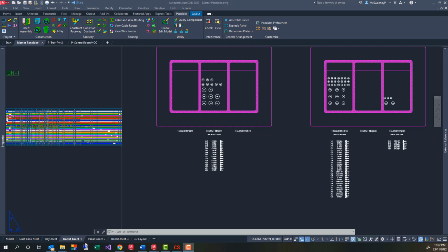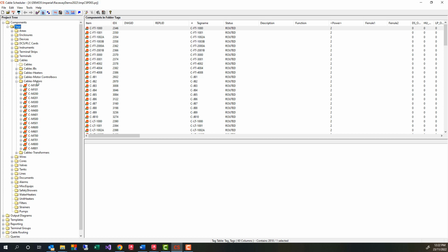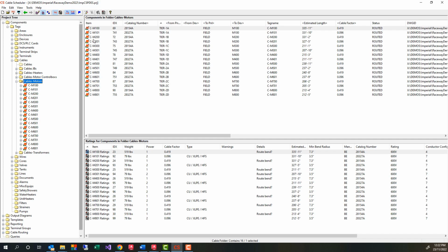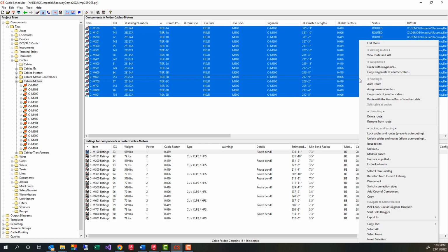Cables are best staged in batches and best managed when organised in folders. It is highly inefficient to try to work in a spreadsheet with 10,000 rows of data. In a project from the early stages, you can often design Raceway and route cables before other parts of the plant are finalised. Examples are underground systems must be designed before the above-ground raceway, or in a high-rise, cables on the top floor are normally pulled last.